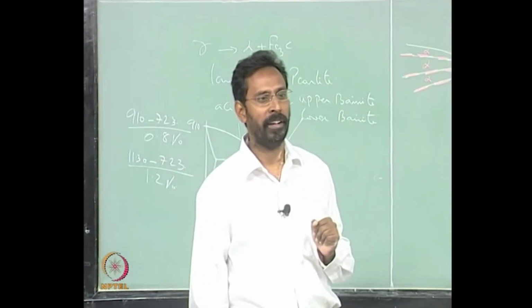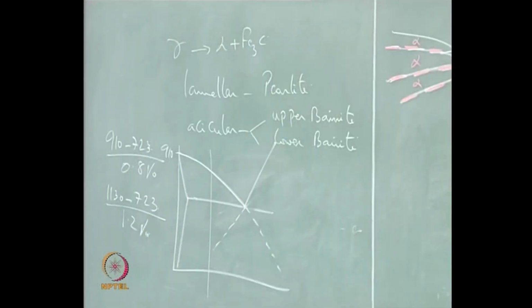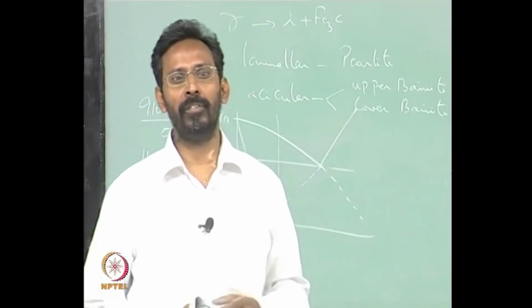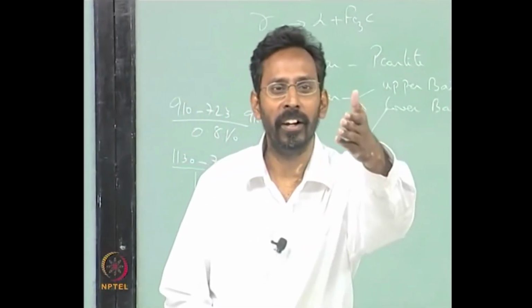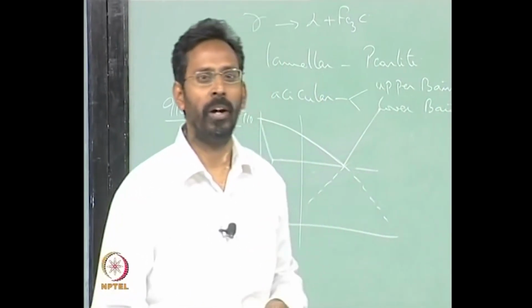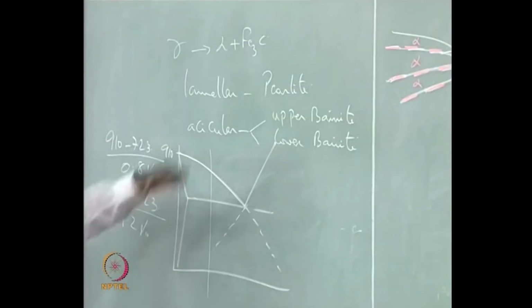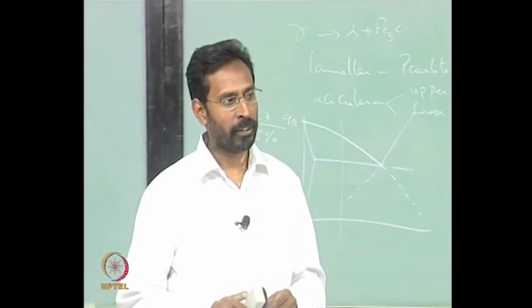What is the advantage, tell me? If I heat a steel to very high temperatures, what is the advantage? Physical metallurgy, if you are thorough you will know. Yes? Coring, why are you talking of coring? Okay, let us not bother, we are talking about heat treatment, in terms of the microstructures, coarser grains. So toughness will be better, coarser grains,